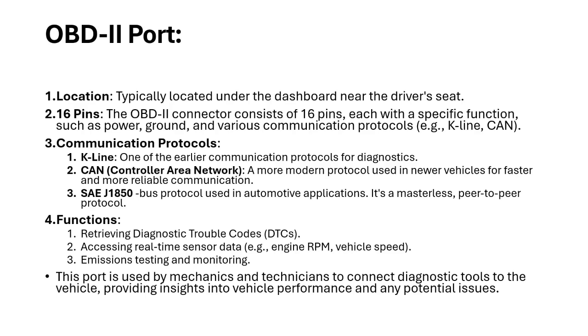OBD-II port. It is a port used to communicate with the OBD system. It is usually located under the dashboard near the driver seat, below, near where the fuse connector is. It is a 16 pin connector.